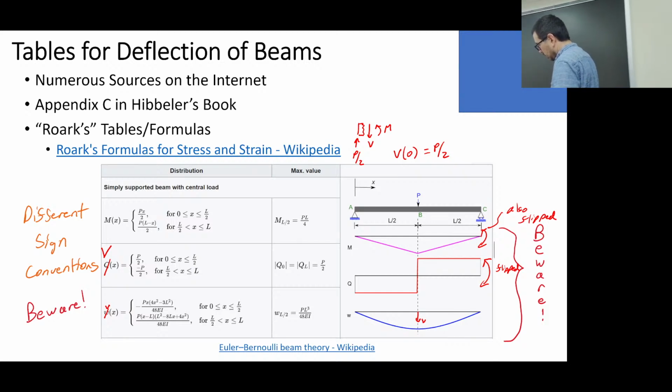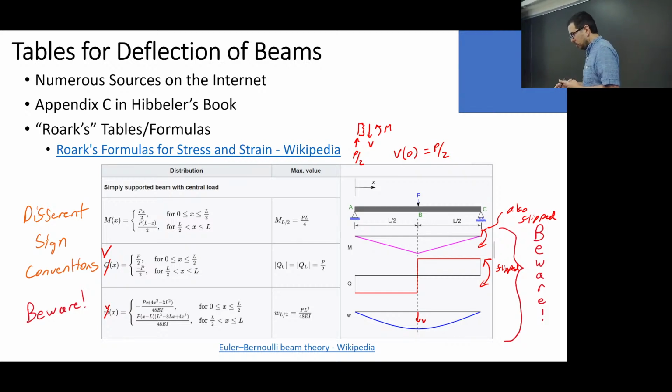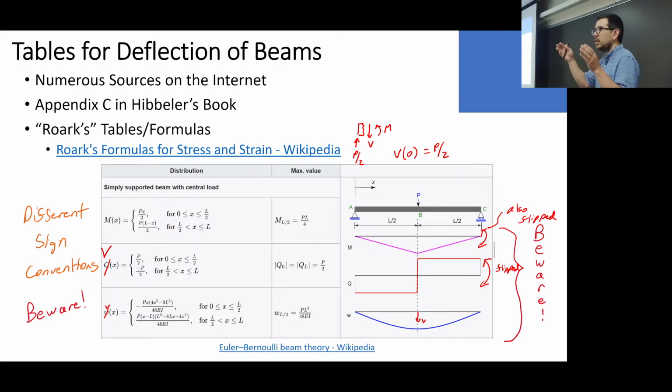And in Pibler's book, little v, the displacement, is positive when it's up, not when it's down. But it's very common that you'll see in these other books that they define displacement as positive going down. Why? Well, gravity works downward, so often you've got a mass working under gravity sitting on top of a beam. So that's why you usually see the books writing the forces that are applied downward.